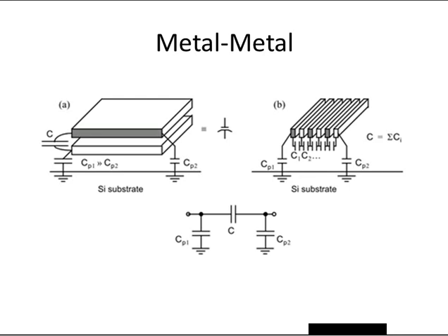So for example, if it's a resistor, we might have a 5K resistor that we've characterized. We understand its parasitic capacitances and what the model for it looks like, and we're going to build everything out of those 5K resistors. If we need a 50K resistor, we're going to put 10 of them in series. If we need a 2.5K resistor, we're going to put 2 of them in parallel. Okay, that's going to give us good matching and good consistency in our modeling. So again, just as with transistors, don't assume that you have infinite control over the precise value of these components.